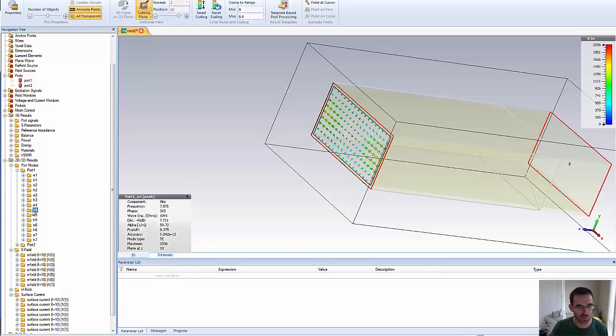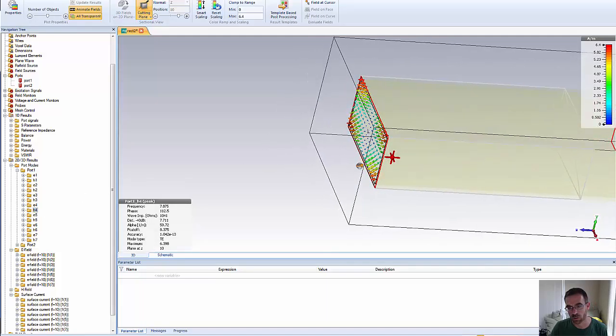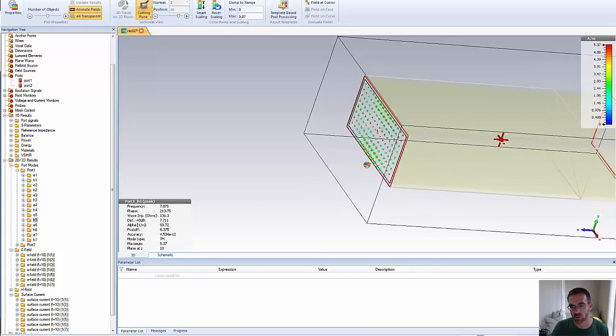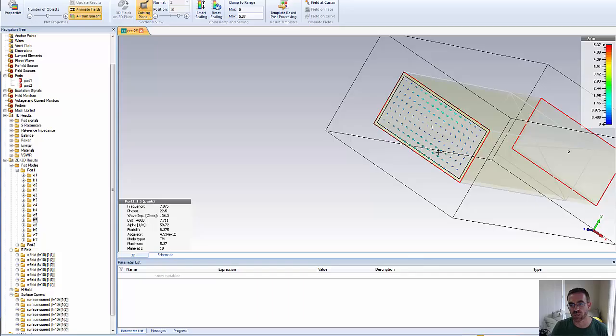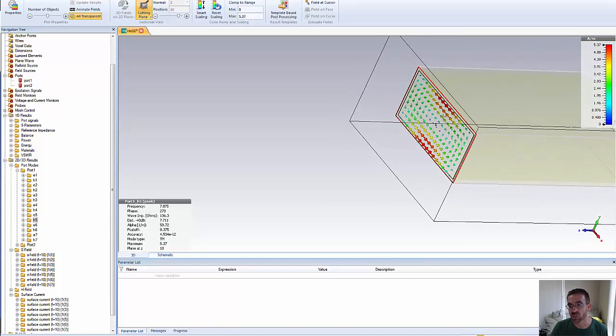This looks like it is a TE11 mode because the H field has a Z component. There should be a TM11 mode. And now what we see here is a circulating magnetic field. Freeze that. Notice the H field is going, at this point in time, rotating in a clockwise fashion. I wait 180 degrees, and now it's rotating in a counterclockwise fashion. But now H is circulating around, and since I have this rotating H, I expect to have a Z component of the electric field.